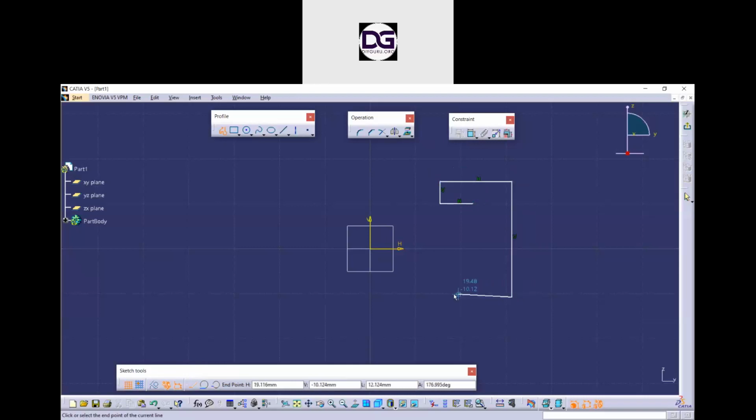Also, these blue lines that we can see indicate certain points. If I want a horizontal line, this line will be turned blue and it shows me that my line is horizontal. And if I drag further, there's another blue line coming from the top. That means now this point is in line with the vertical line. And I want that. I will click here and drag this upwards, and you see, if I change the direction of my mouse, the blue line disappears, and when I'm vertically above that point, the line turns blue. That means this line is vertical now.